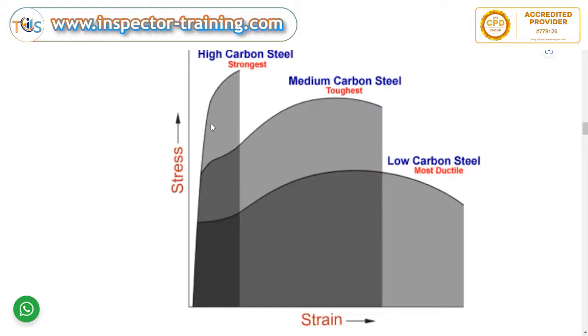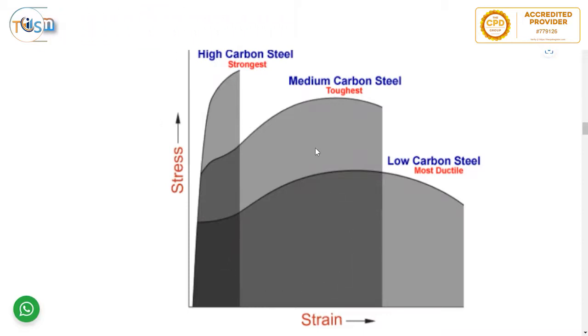But as you can see, the area under its stress-strain curve, or the energy absorbed, is the least. You can see the second material, both its strength is good and also its strain. It took a lot of load while straining until it breaks. So this got a large area of toughness compared to the other two.